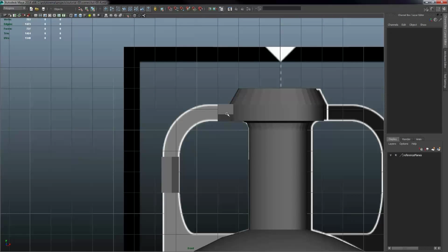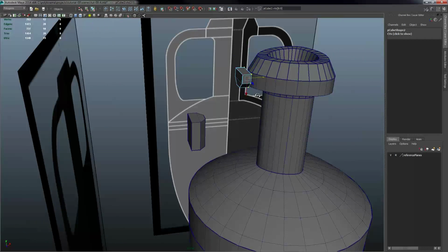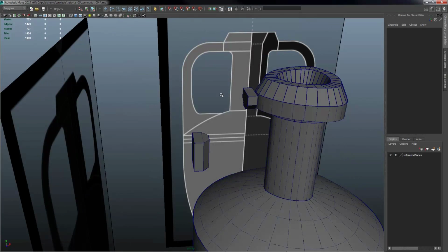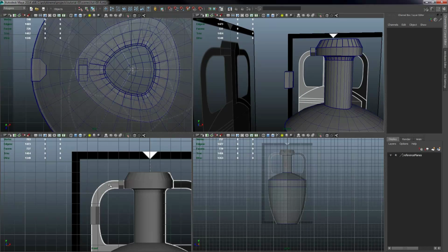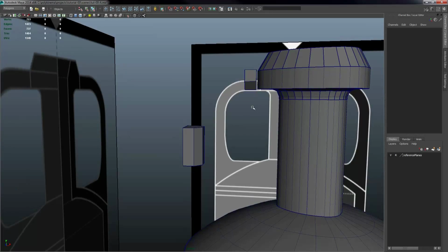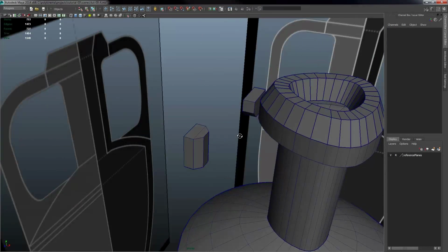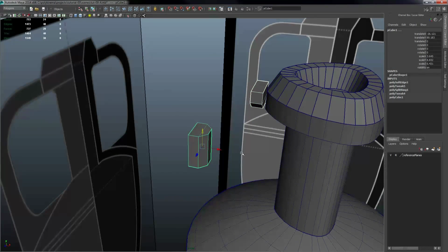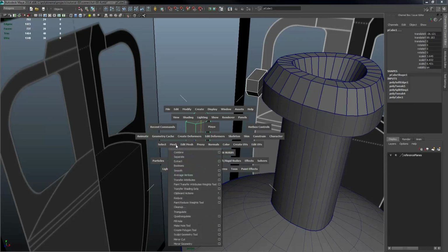along this grid line is where the form stops being a curve, so I can align it to the grid there and bring this edge in so it just about touches. I don't need it to touch perfectly yet. So I want to create this sweeping curve. I'm going to do that using the bridge tool. I'm going to combine these shapes together, mesh combine.